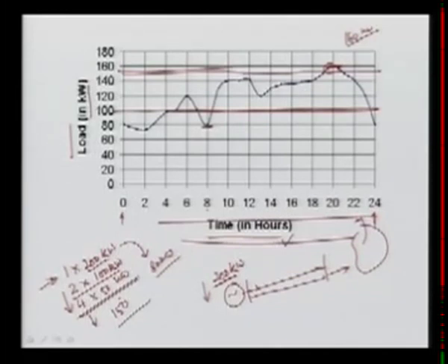If you are going for 1, then the capital cost per unit kilowatt is less compared to 4 units. So the cost of installed capacity will be reduced. At the same time, the operational and maintenance cost will also be less, because with 4 units you have to maintain 4 units, whereas here it is only 1 unit. So maintenance cost will also be less. So there is always a compromise between a smaller unit or a larger unit.